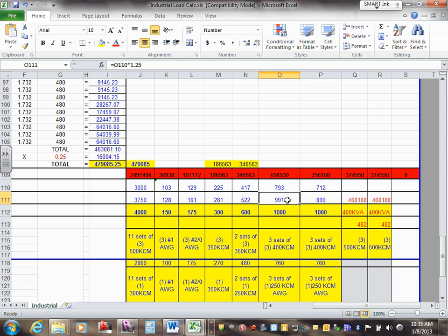They tell you that there is a 1,000 amp busway. We're just on the busway, we're not actually putting it out. No, it's just a busway. And if you guys go here, pages 3-12 and 3-13, the busway sizes and the panel sizes are right there. So you size it like we did in the commercial project. The same thing for the 208. I end up with also 1,000 amp for the 208.